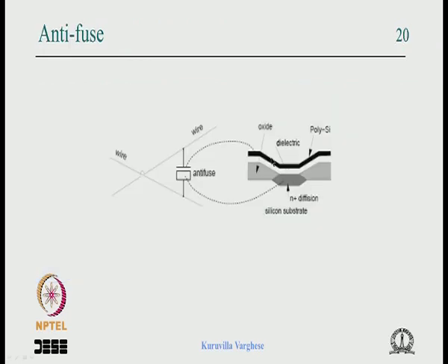This shows the horizontal wire on the top layer, and this shows a vertical wire coming out of the screen towards you. So there is a hole with a proper deposit, and you apply a high voltage. When I say high voltage, I mean nearing 10 volts, and then it fuses and makes a connection, which is permanent and cannot be erased.